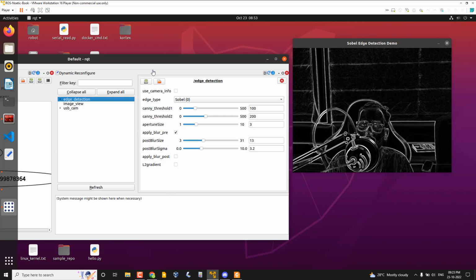We can change it, but there is some problem with that, because if you want to see the change of some process after changing the parameter value, for example, I have a color detection program. If I want to change the threshold as a ROS parameter, then whenever I change the threshold, the detection has to change. So a normal ROS parameter will not do the job. So for that, ROS 1 has dynamic reconfigure.